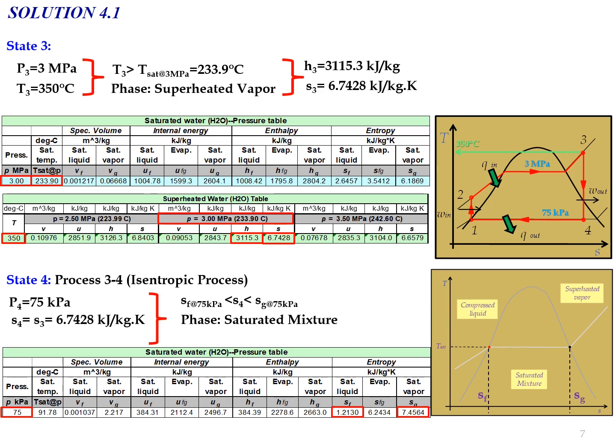Now, when the phase is saturated mixture, we cannot determine the value of H directly from the table. As we have learned in Thermodynamics 1, we need to determine the value of H by using a specific equation, and also we need to determine the quality of the steam, the value of X, before we can determine the value of H for state number 4.